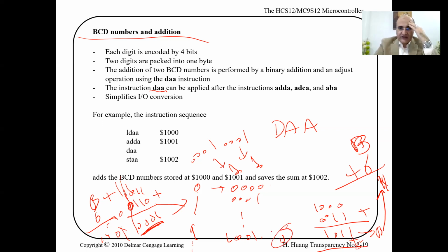Instead of doing this, adding the 6, you can use the instruction DAA. DAA will adjust the last result in the accumulator by adding 6 to it. Okay. Yani, instead of you adding a 6 by yourself. Why 6? Because the numbers after 9 are A, B, C, D, E, F, then you go back to 0. You roll over back to 0, right?